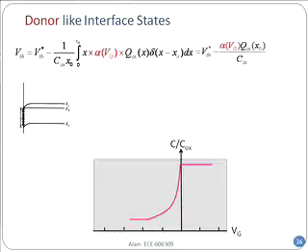However, what happens as you go up, by the way, on the top side I have written alpha Vg multiplied by Qox, because this amount of charge, depending on the bias, will be changing. And so alpha, the fraction of the total number of defects that contributes to the charge, will be changing depending on the bias there.